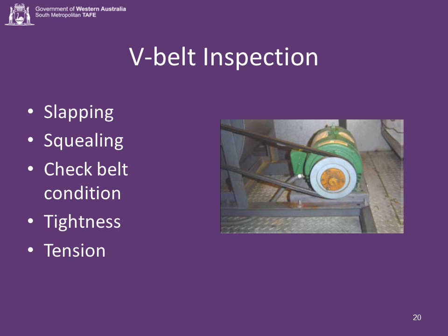Maintaining correct tension is the most important rule for V-belt care. Belts too loose will slip, causing excessive belt and sheave wear. Belts that sag too much are snapped tight suddenly when the motor starts and when peak loads occur. This can actually break a belt.